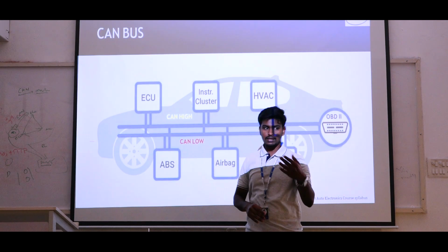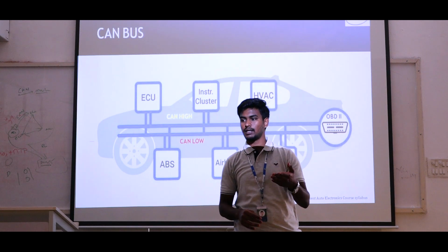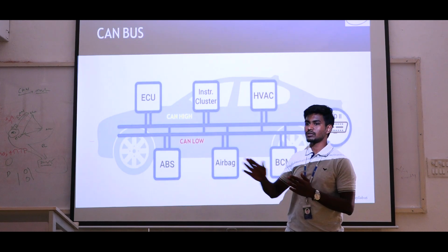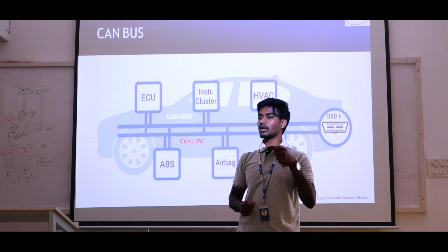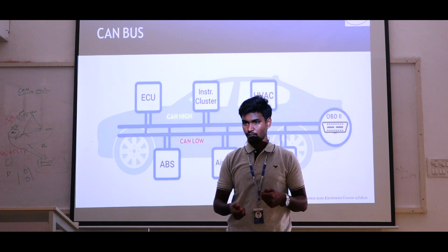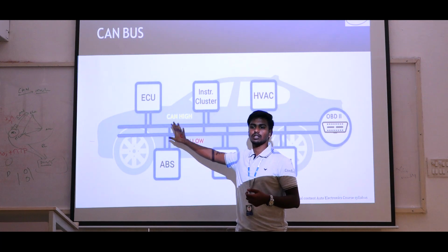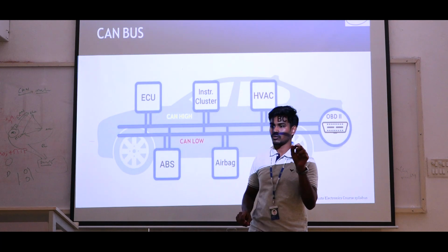Other protocols like LIN, FlexRay and Ethernet will take more than 2 wires. So why are we using CAN? It gives more advantages to easily identify errors. For diagnostic purposes, we can easily diagnose using only 2 wires. It is enough to work with the 2 wires.